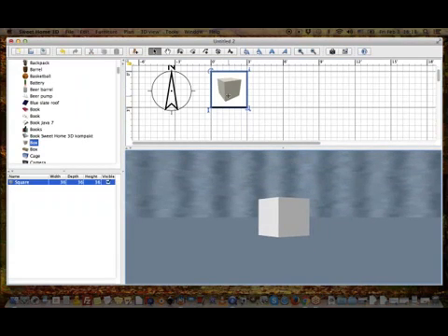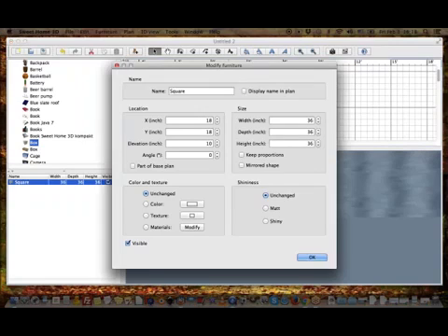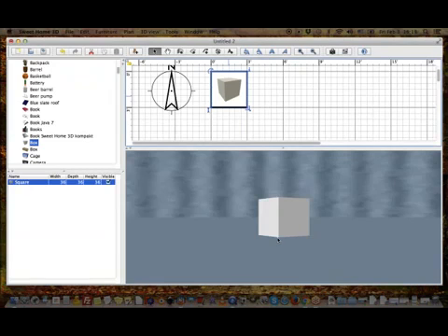Okay, so this is where you control the elevation, meaning the position. Now the elevation works differently from the other registration points. The registration point for the elevation is the bottom. It's right here. So when I enter a number 10 for the elevation, it means that there are 10 inches between this cube and what is considered the ground in Sweet Home 3D.